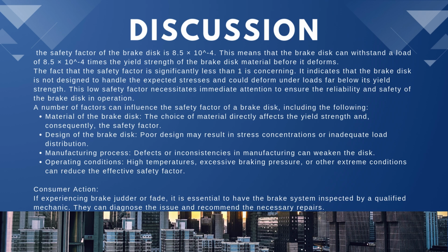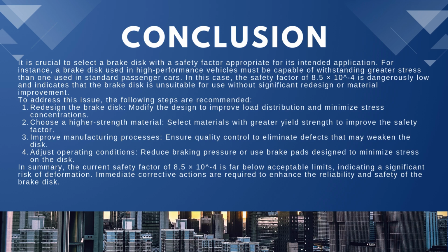Consumer action. If experiencing brake judder or fade, it is essential to have the brake system inspected by a qualified mechanic. They can diagnose the issue and recommend the necessary repairs. It is crucial to select a brake disc with a safety factor appropriate for its intended application. For instance, a brake disc used in a high-performance vehicle must be capable of withstanding greater stress. A low safety factor indicates that the brake disc is unsuitable for use without significant redesign or material improvement.